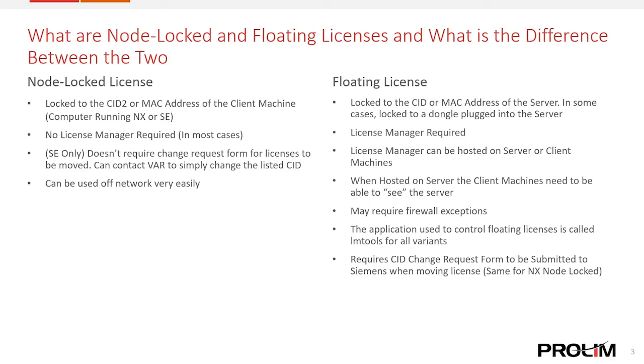And this is just to avoid little issues like messing up the licensing server by having it on the wrong service while having it launched from the wrong location, and everything gets wonky. So just for the sake of consistency and to keep everything nice and easy, I like to do it that way, because you can run into issues when running the same LM Tools application for all those different services. So that's my recommendation.